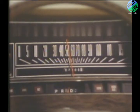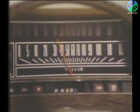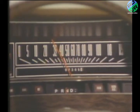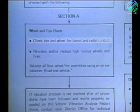Place the transmission in neutral and coast down through the problem speed range. If the vibration is clearly felt, then the problem is probably being caused by out of balance or out of round wheels or tires. Once you've determined that the problem originates with the wheels or tires, proceed as suggested under Section A of the Vehicle Vibration Diagnosis Guide.